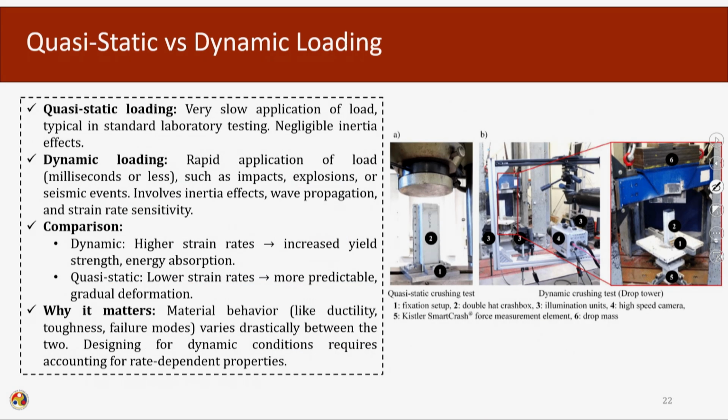Moving ahead, we are very familiar with quasi-static loading. Now we will see a comparison between quasi-static loading and dynamic loading. Quasi-static loading: nothing is truly static, therefore we are terming this as quasi-static loading. It is a very slow application of load, typical in standard laboratory testing. So, the inertia effect is not engaged.